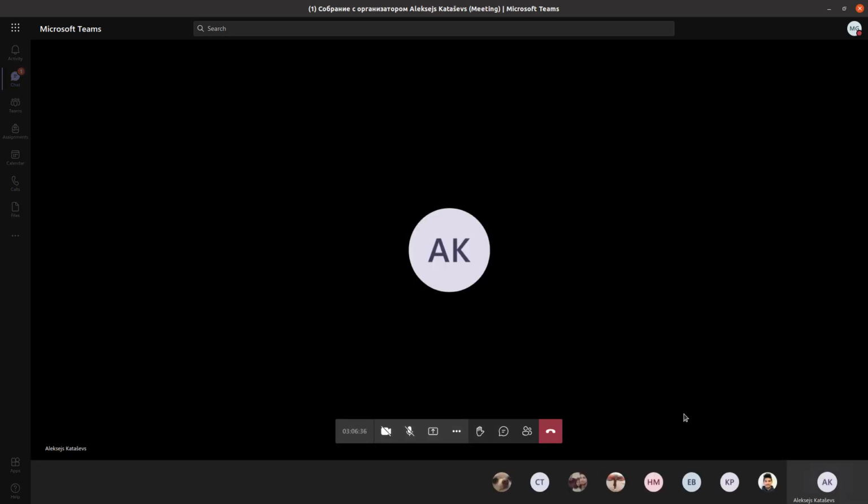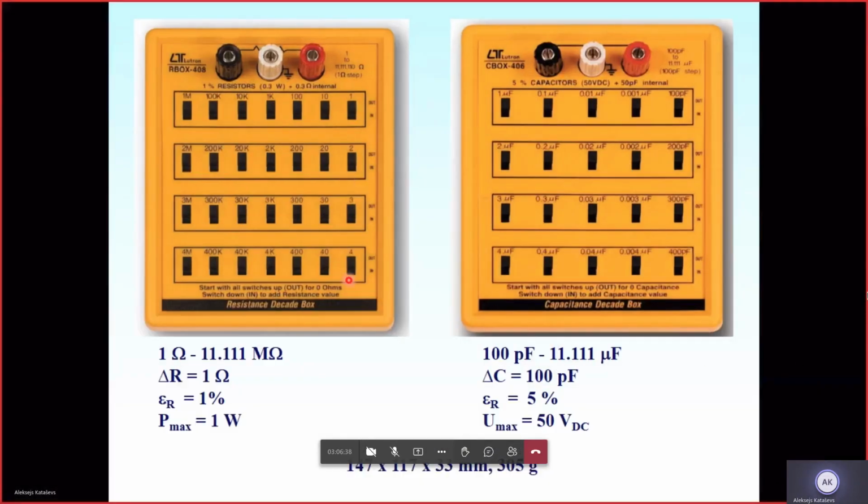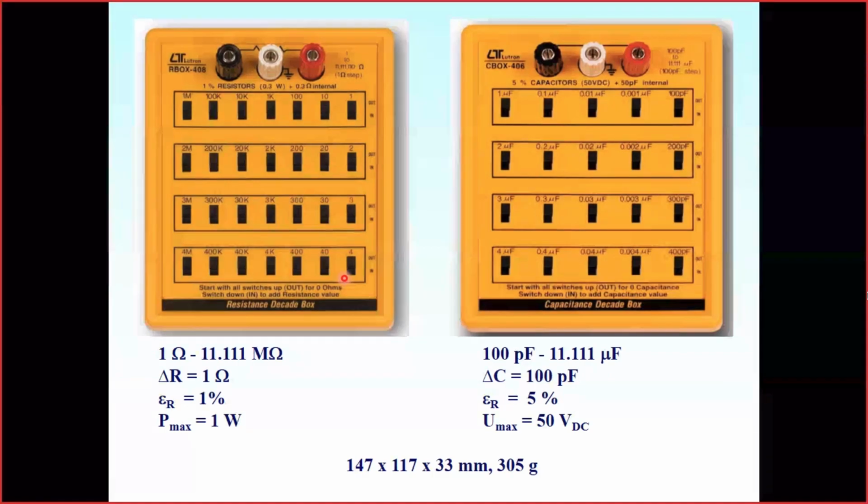One ohm, 2 ohm, 3 ohm, and 4 ohm. This is enough to get whatever value from 1 up to 10. If we add all these together, 4, 3, 2, and 1, we get 10. So one decade may provide values from 0, when all the switches are off, up to 10 when all switches are on. This design of switches is not very convenient for working with a bridge,